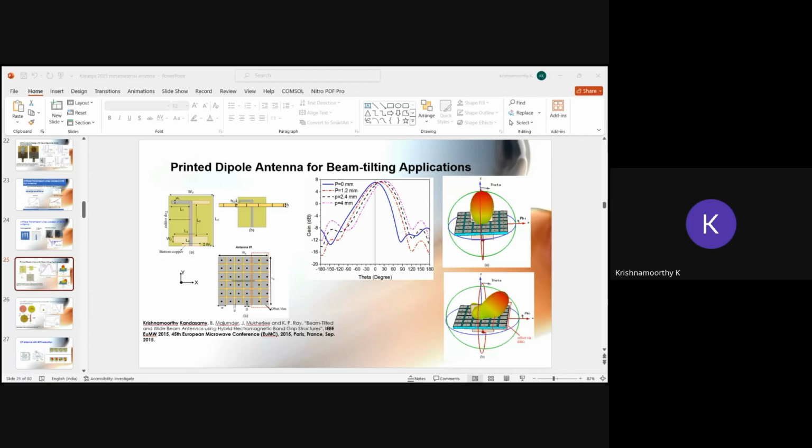Achieving the metamaterial characteristics, negative mu and negative epsilon, depends on the dimensions related to the wavelength. So accordingly, when you change the length of the structure, the characteristics shift to different frequencies. So all the characteristics are wavelength-related.